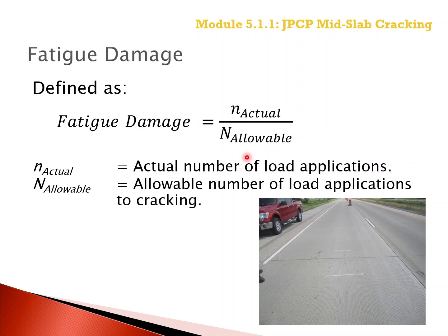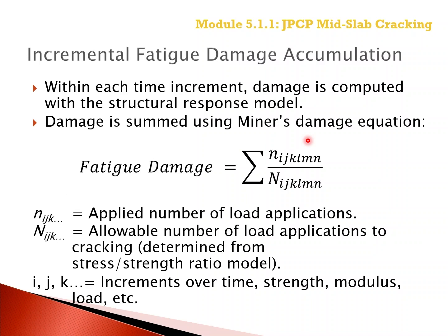Remember from Module 2, the fatigue damage is the result of the actual number of load applications divided by the allowable number of load applications, just like what was demonstrated from the paper clip experiment in Module 2. The incremental fatigue damage is summed using Miner's hypothesis or damage equation, which is displayed on the slide.